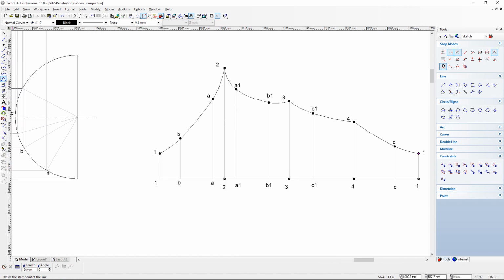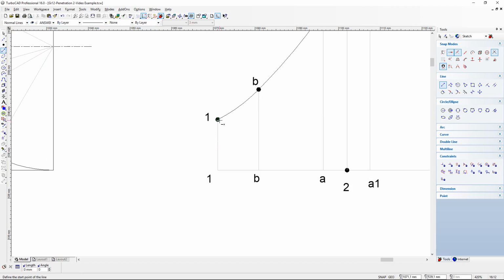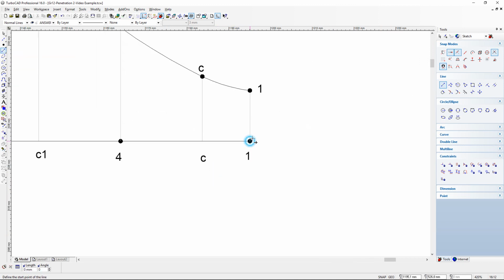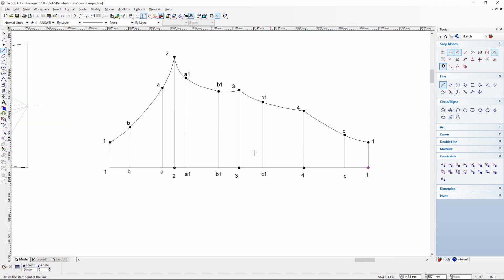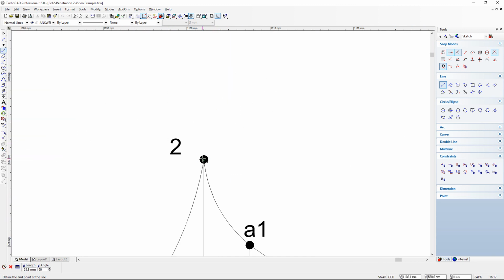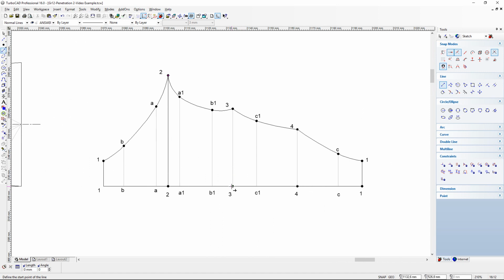All that I need to do is now draw solid as an outline as well, the base and the outer edge of my development. So from number 1 all the way through to number 1, because what we started with is what we end with. And if you worked correctly, you will see here is the full development of the prism. And one last thing that we need to do is, because we have used a square prism, at each segment we obviously will now have a fold, and therefore we will draw a solid line there.